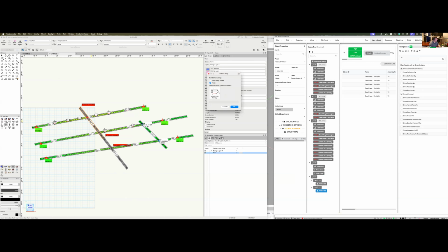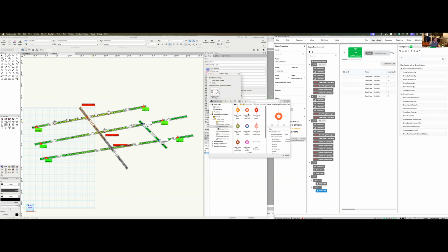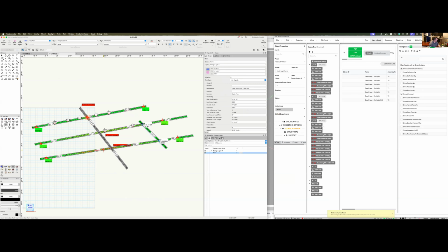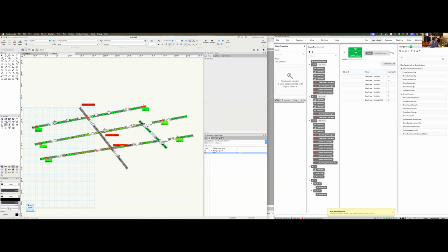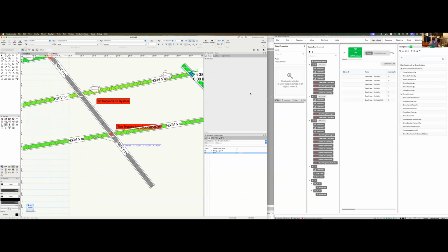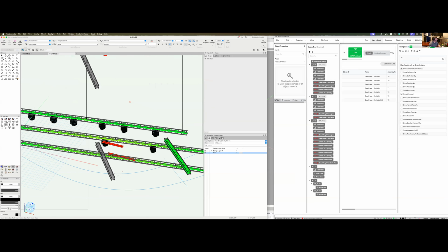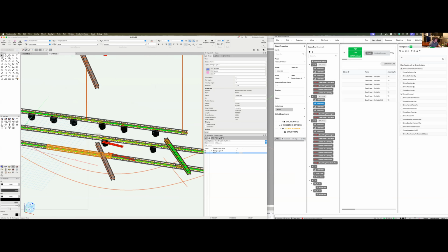This truss remains fixed in position. Then, select the truss you wish to drop relative to the base. The system automatically calculates the appropriate vertical offset to create the desired gap. This feature is ideal for designing rigs where precise vertical separation is required, enhancing both flexibility and safety.